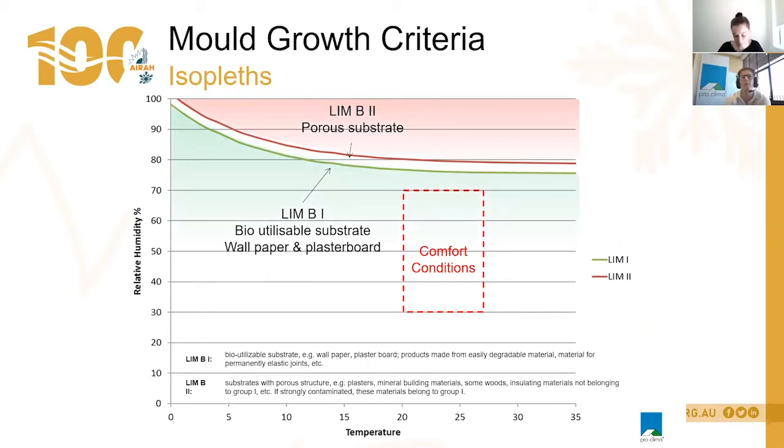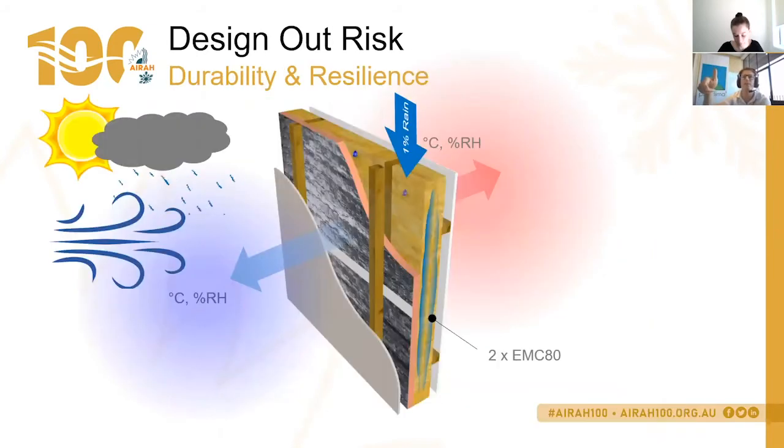So if we then take a structure and you're going to analyze a structure using the criteria in DA07, you might want to look at all the different aspects: built-in moisture, rain leaks, just normal operation. You can analyze with and without rain leaks or with and without built-in moisture. But either way, you can do the analysis.